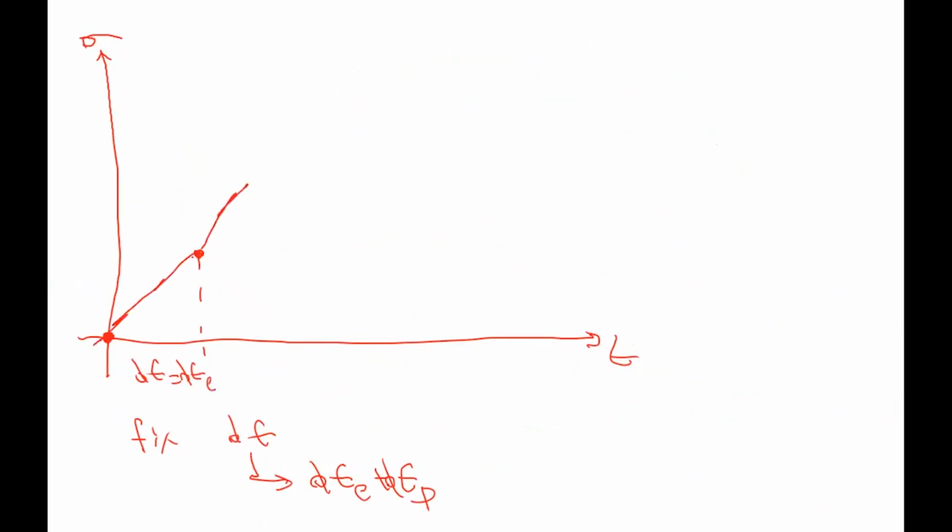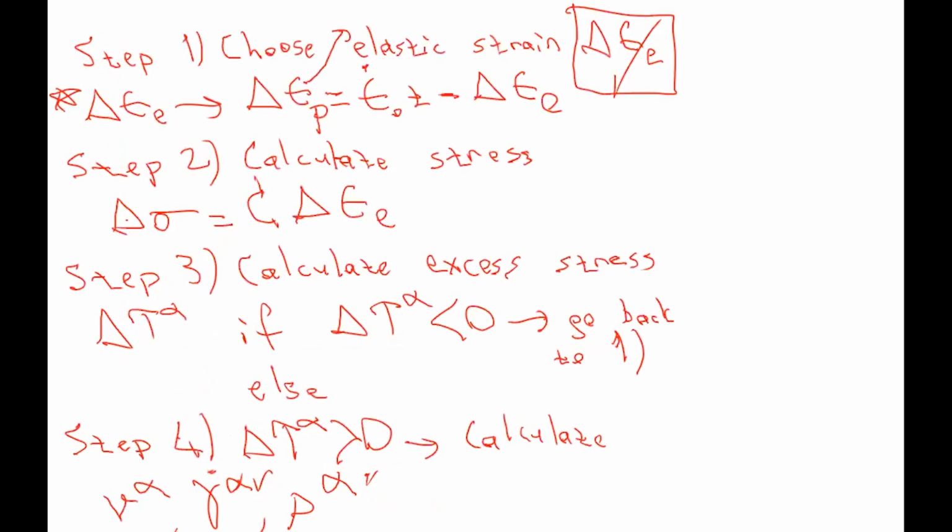At the second stage also, you calculate the stress, and you see that it is less than lattice resistance, then you don't have any velocity, then your plastic strain is 0, and the fixed amount of strain, the epsilon, is equal to only elastic strain.